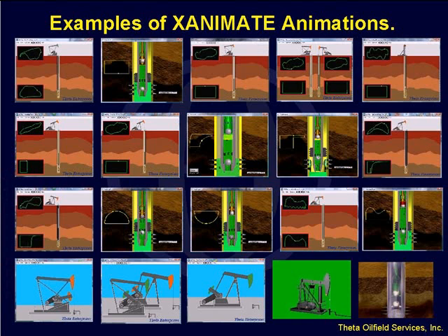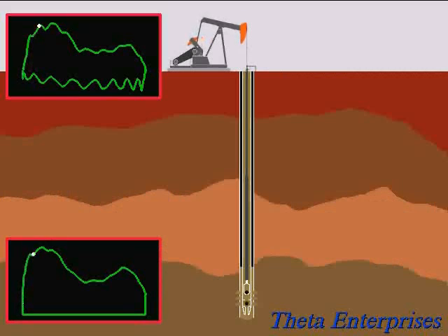Another interesting animation is when you deal with shallow high rate wells. We call these group 2 wells with fluid inertia effects. These occur when you have typically less than 4,000 foot deep wells with a larger plunger, like 2 1/4 or larger. The dynamometer card for a full pump is no longer a rectangle. It has typically a hump on it like this because of the fluid inertia effects.